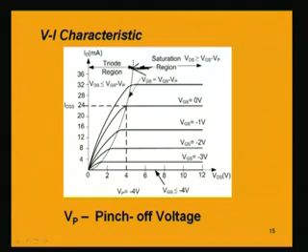As we go on increasing VGS from bottom to top, the saturation is shifting towards the right and right, at a higher voltage the saturation is happening. And when the drain to source voltage is less than VGS minus VP, this region is known as the triode region. So, we have cutoff, then triode, then saturation regions, these three regions.